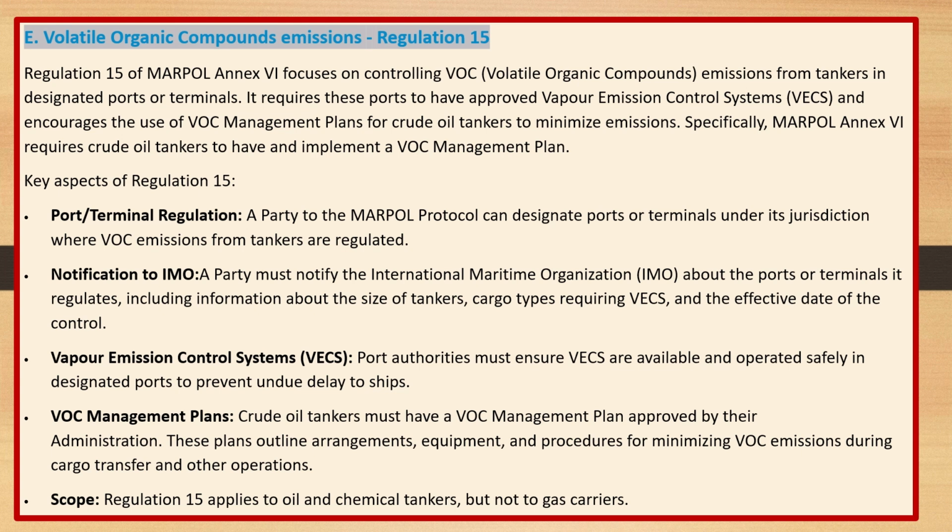Vapor emission control systems. Port authorities must ensure VECs are available and operated safely in designated ports to prevent undue delay to ships. VOC management plans. Crude oil tankers must have a VOC management plan approved by their administration. These plans outline arrangements, equipment, and procedures for minimizing VOC emissions during cargo transfer and other operations. Scope. Regulation 15 applies to oil and chemical tankers, but not to gas carriers.